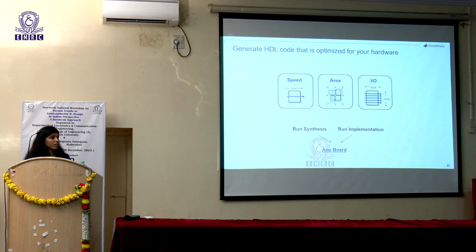One more thing you can do is, even if you don't have a particular board, say you want your algorithm to work on Zynq 706 or any FPGA, you can choose that board and run synthesis and implementation. You don't have to open the Vivado tool to do all this. It's all automated through HDL Coder. So you can look at the synthesis or implementation results, what frequency you are able to achieve or what kind of resources it is consuming. If you want to improve your design, you can go back to your Simulink model or your MATLAB code, change it, and do the same thing again. So you're not shuffling between apps, loading and unloading projects. You don't have to do all that.